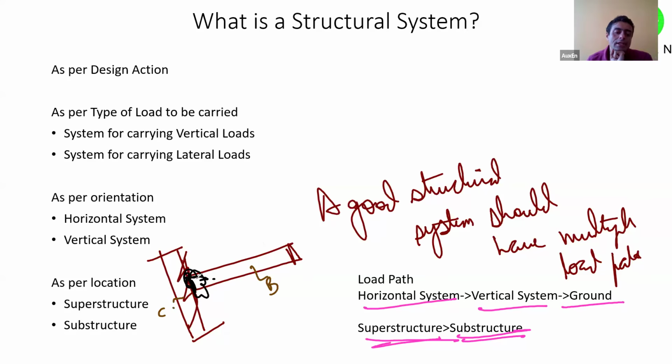So suddenly, let's say the reinforcement slipped or there was some failure at this cross section, then will this cantilever beam remain stable or will it remain in equilibrium? Tell me. Hello. So the answer is no. If there was to happen some failure at this junction between the beam and column, this cantilever beam would just fall down, isn't it? It would no longer remain stable.